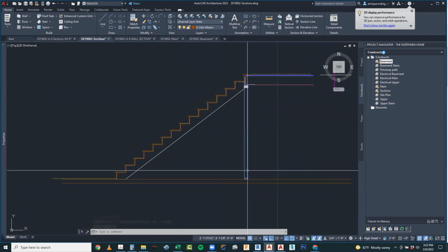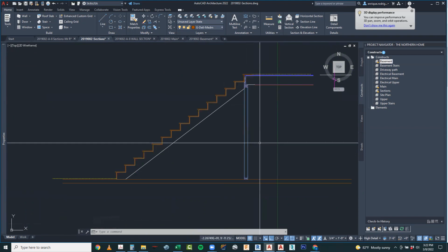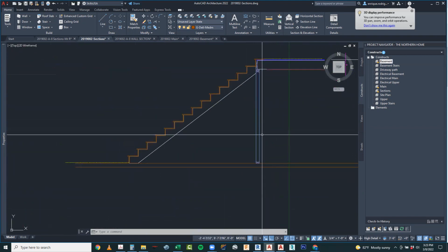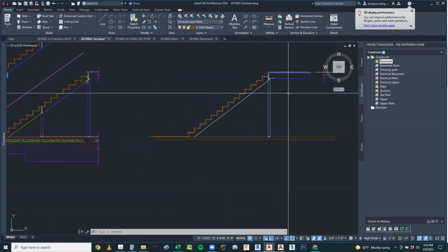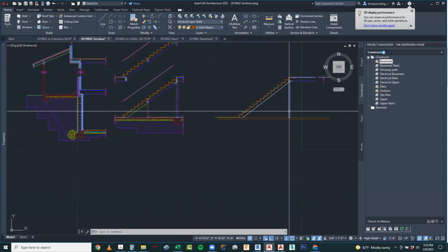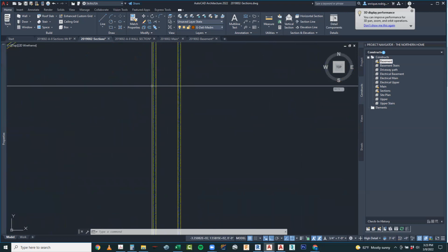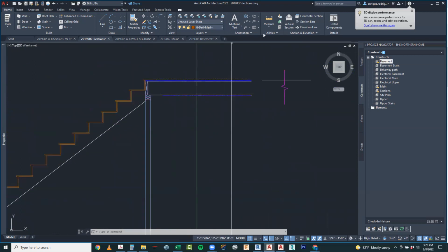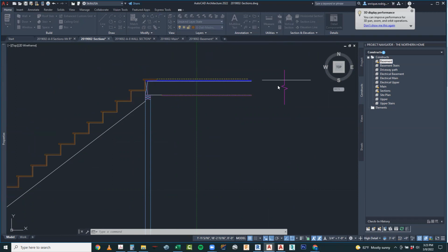Now let's continue and let's see what we got happening on this wall. This is actually what's called a bearing wall. A bearing wall means that it's taking load. So this is a 2x4, means that your studs need to be closer together. We're going to go ahead and put drywall on both sides of it. So I can go to the detail components. Wait till it opens up.